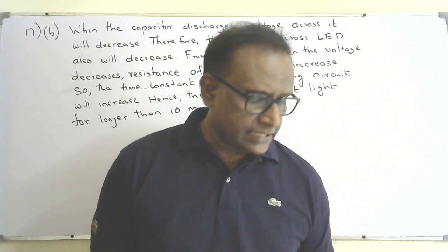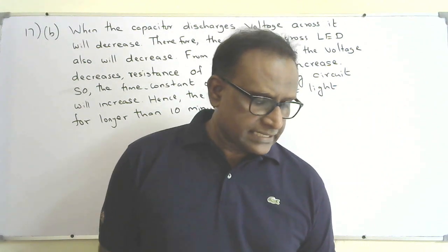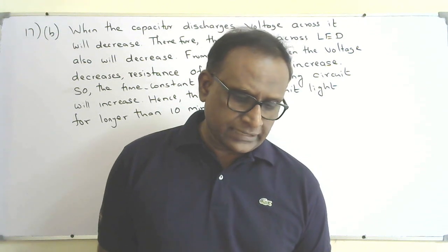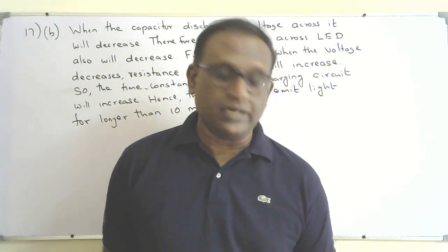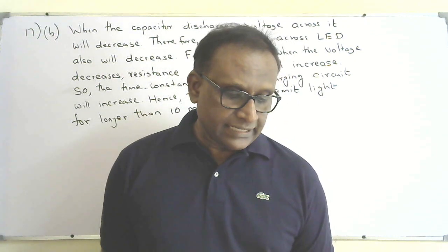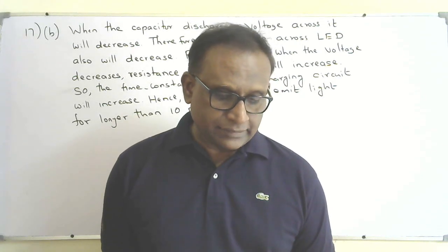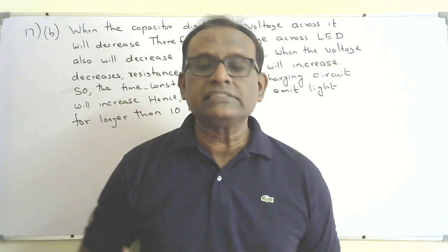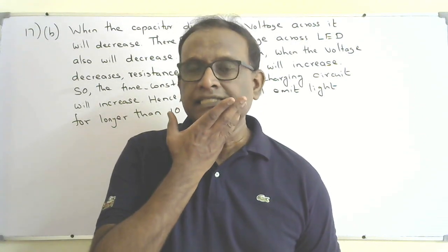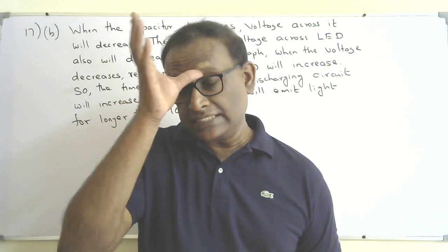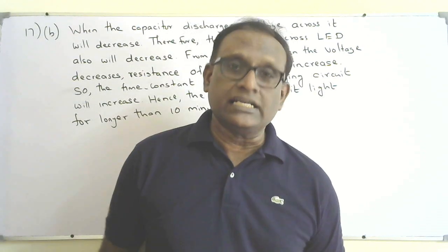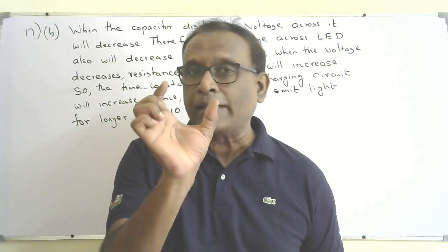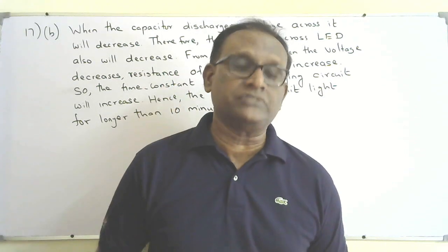Okay, part C, question number 17. The student states a capacitor is being used in this circuit. The function of the capacitor is to store electric charge. Explain why this is not a complete description of the function of the capacitor. Actually, when you are storing charge, it stores charge on one plate of it. So when you consider the whole capacitor, there is no storage of charge.